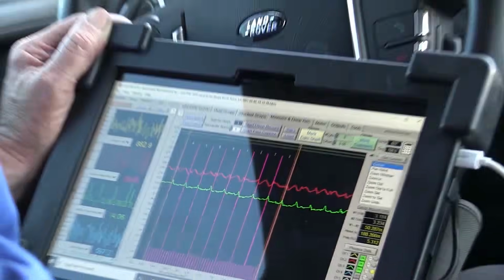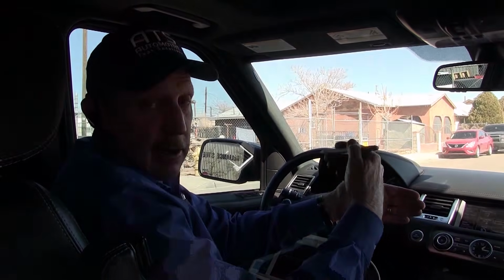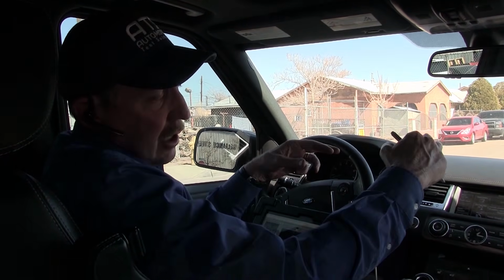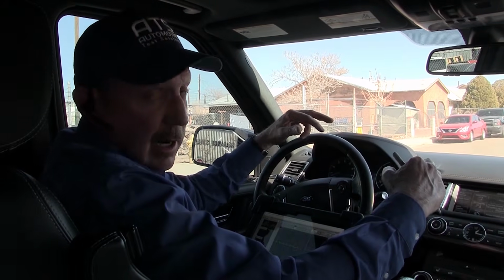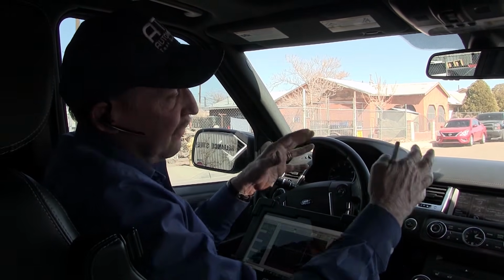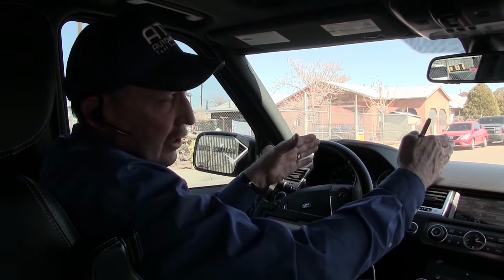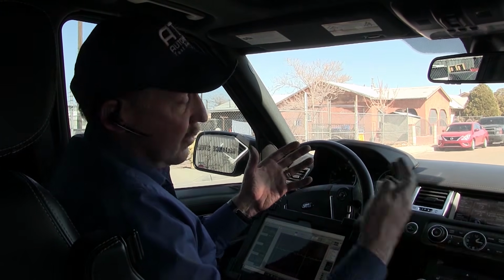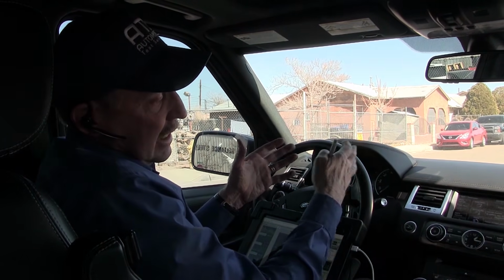Now, each pump is going to fire the firing cycle. But this firing cycle fires 2 cylinders on one bank in a row and these 2 on another. So one pump feeds 2 cylinders on each side, so this wouldn't be a cylinder side issue. There's no way I can see that, okay?